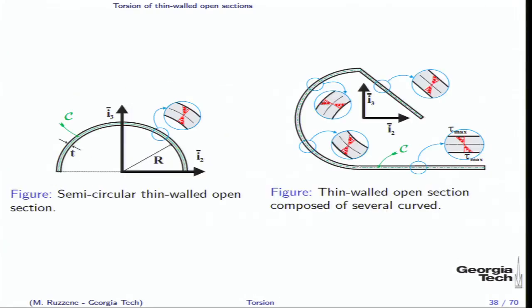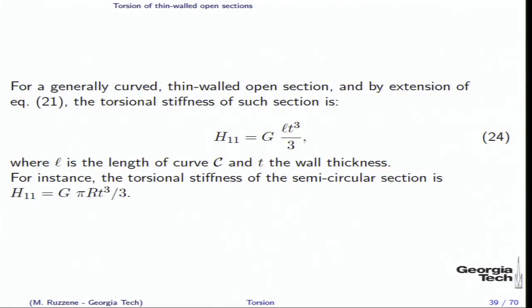And the variation, as we saw in the previous slide, is very minimal along the length coordinate of that curve. There will be a variation in the normal plane. So whenever you see a thin-walled section, you can make a normal line through the thickness, and there will be a linear variation in the shear stress in that component. And similarly for all the regions in the cross section.